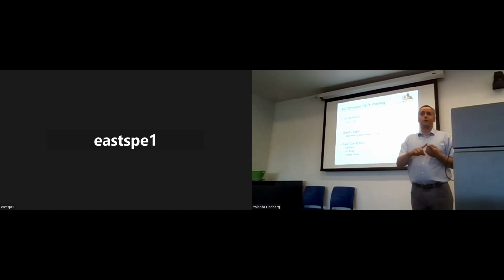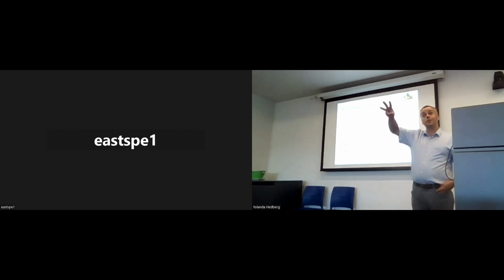Now I've got to hire a consultant who's going to use sophisticated modeling to measure the distances between ground, when the phases change angles, how far a distance they are from a pipe, what grounding they have, what shield wires they have, when our pipe and the power line deviate, when they come together, when they cross, when the phases change, when the soil changes.